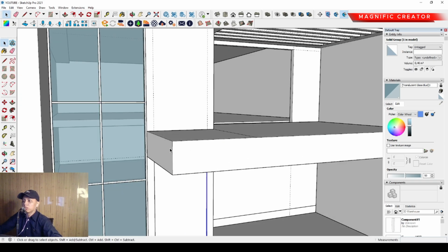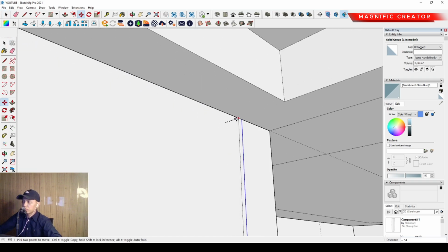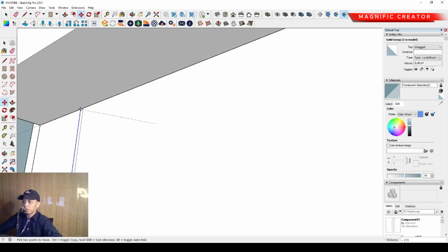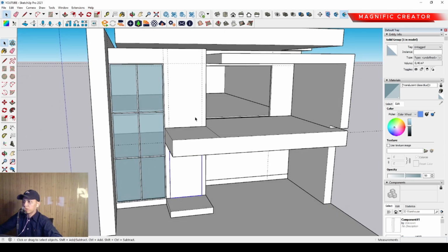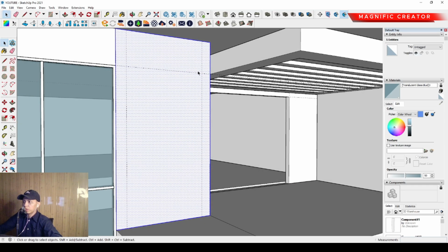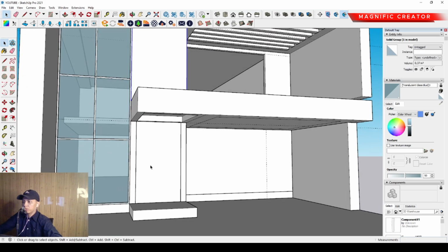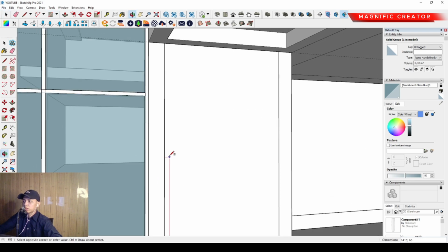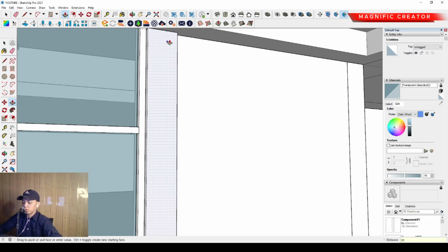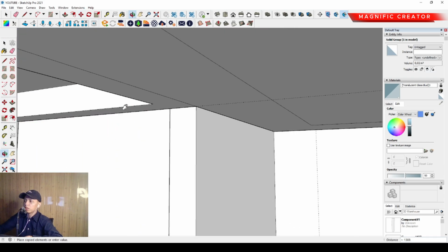And then anyway we can make another component, or maybe we can just make it the same. Okay, we can make it the same level, and we have to adjust it again. Okay, so we can make another wall element. Start using this line until this position. Okay, so then we have to push it to the front around 50 millimeter. We can make a group. Okay, so we can make another component of it. Start from here to here. Then we can push it to the front around 30 millimeter and make a group. We can move and press Ctrl to duplicate it until this position.